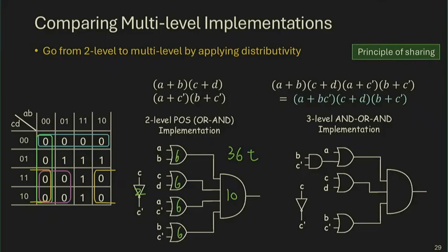When you do factorization, you can factor out BC prime. So this one and this one can be combined into A plus BC prime by applying a little bit of an unnatural distributivity that is only true in Boolean algebra. And then that one will also translate into a circuit implementation. You have 8 over here, 6, 6, 6, 6, and 2. So 24, 26, 34 transistors, which is a little bit better.